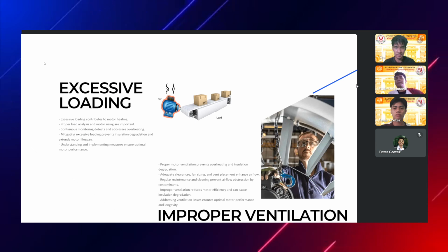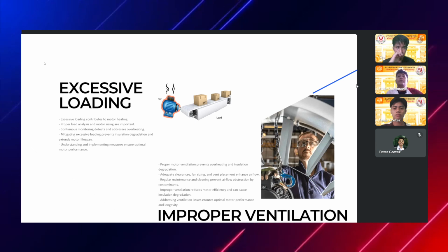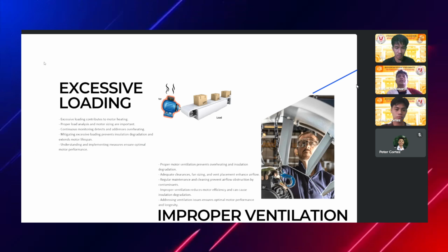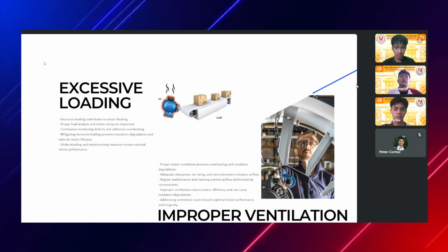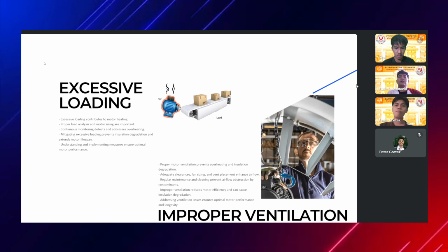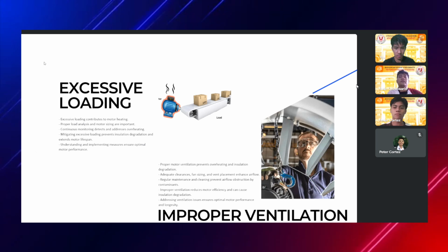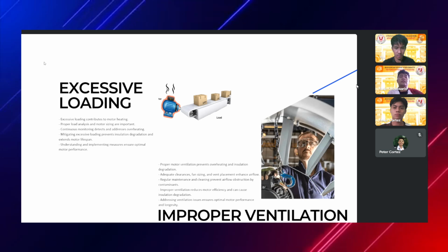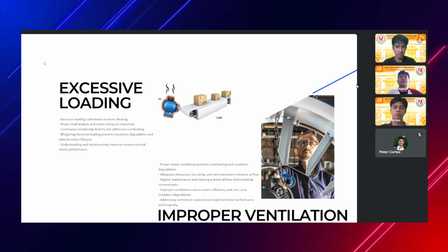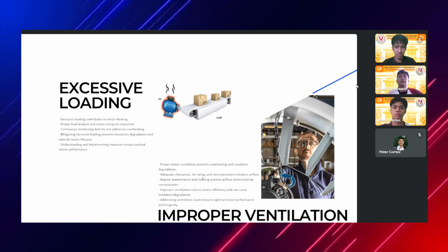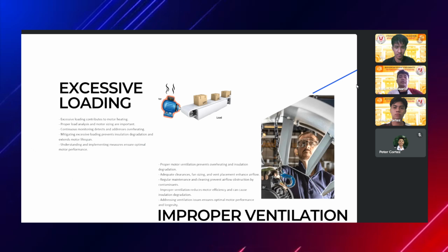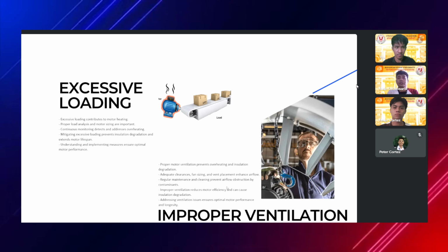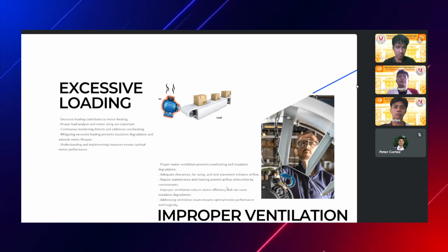For improper ventilation, proper motor ventilation prevents overheating and insulation degradation. Adequate clearances, fan sizing, and vent placement enhance airflow. Regular maintenance and cleaning prevent airflow obstruction by contaminants. Improper ventilation reduces motor efficiency that can cause insulation degradation. Addressing ventilation issues ensures optimal motor performance and longevity.